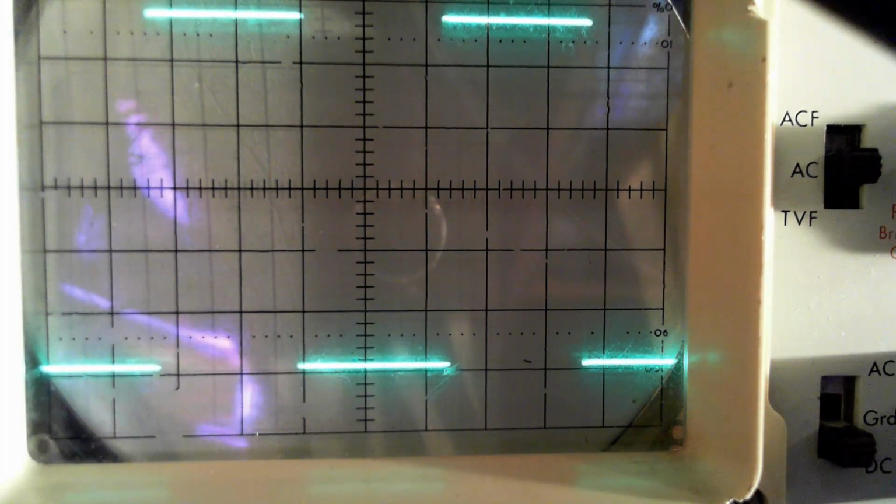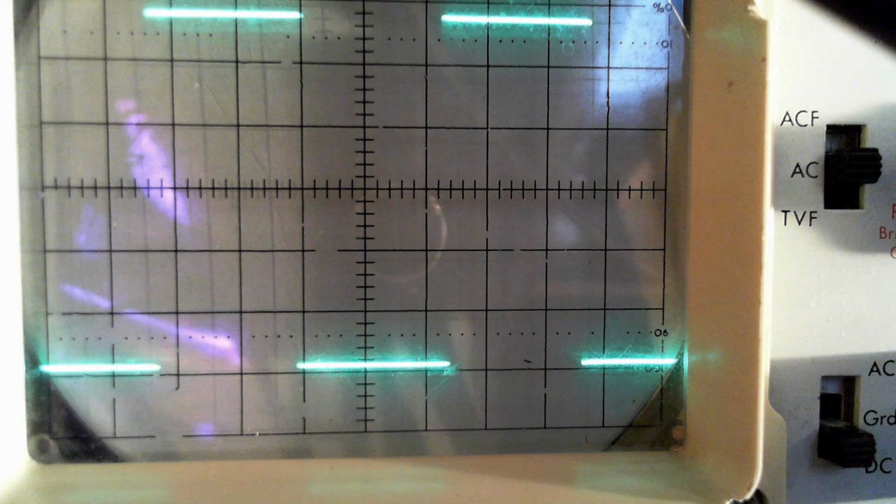Very good. Now the next step is to repeat this, but do it in a different range on the volts per centimeter. And their suggestion was to change the probe and use the times 10 to accommodate this, but I don't think I'm going to do that. I think I'm just going to change the output level on the signal generator. So let me check quickly here what we have to do in terms of the voltage.